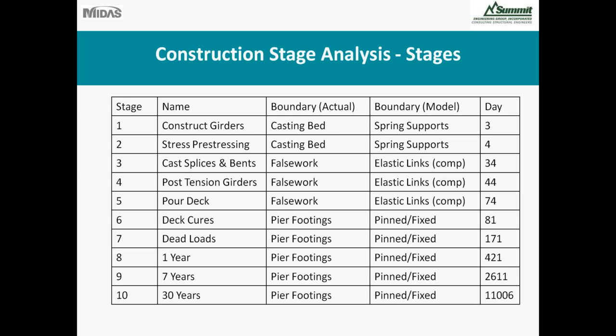The boundaries I used are shown in the fourth column here. I used spring supports for a casting bed, and then compression-only springs once I took them to the field to simulate shoring towers.